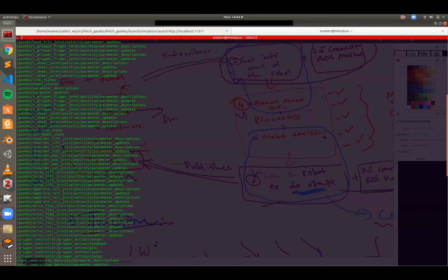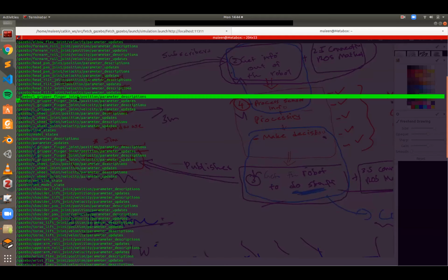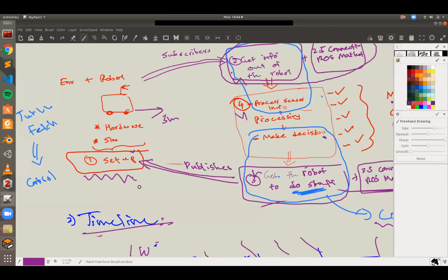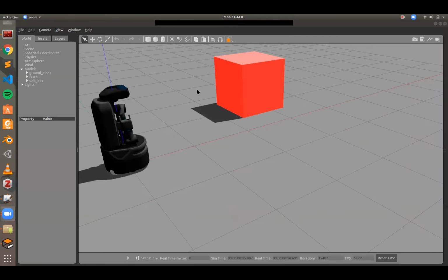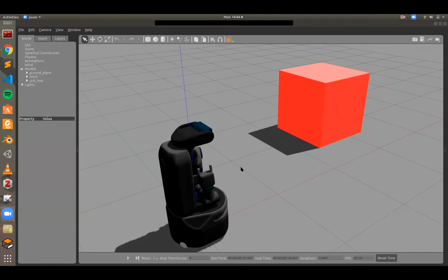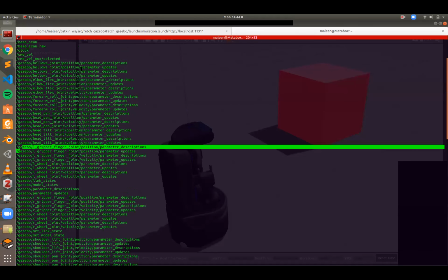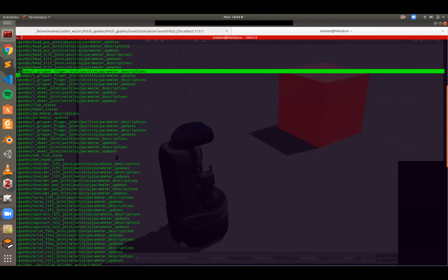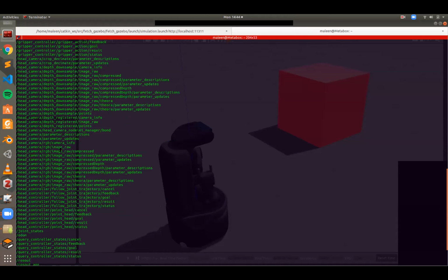So for example, you can see here information about the gripper joint positions, right? So with topics like that, you can publish information back so that you can control, say, the gripper arm and things like that. There are some topics in here that will be sensor information that you can extract coming from the cameras, and if there's a LiDAR, it will be coming from the LiDAR. And then there are some topics in here that have to do with controlling the robot.